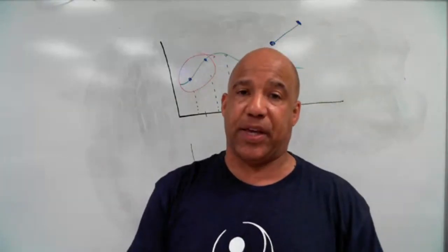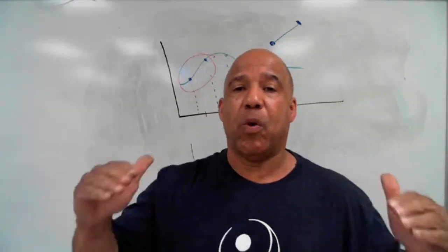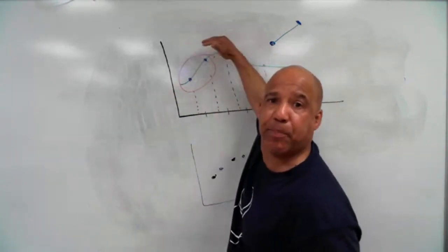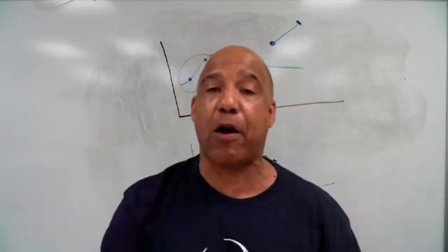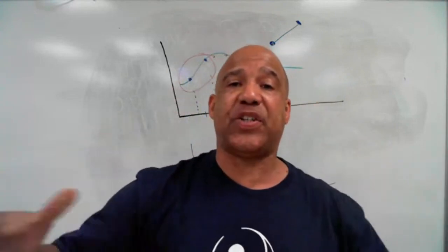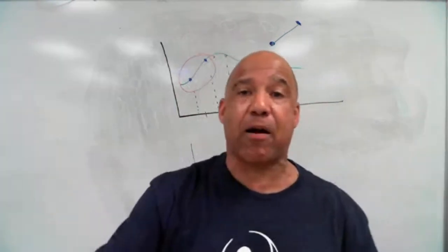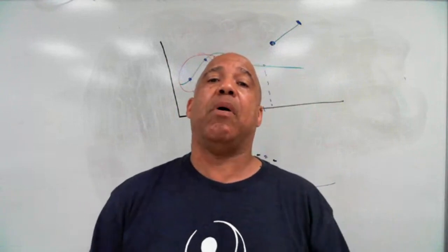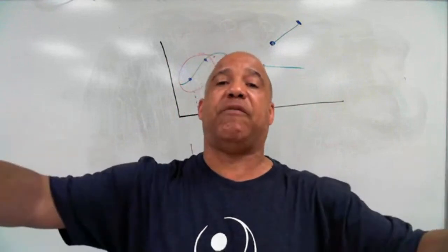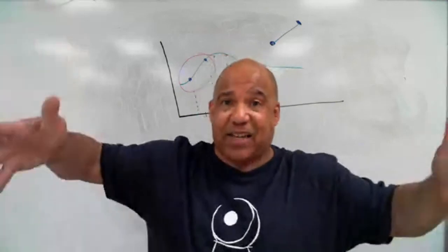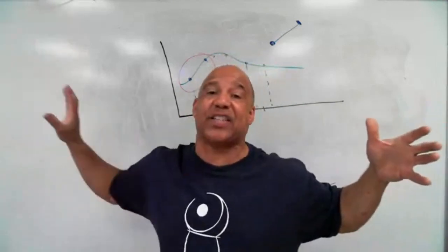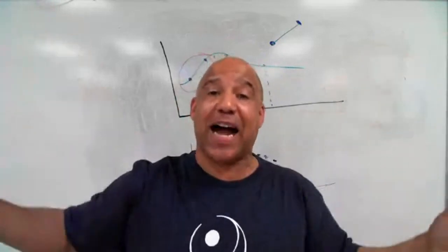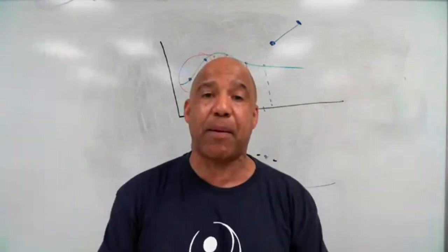The reason we have to talk about this is because of what we're going to do. In the old days, they would actually wire up relays in series and parallel, and I'm here to tell you it was a wiring nightmare. Every time something changed, you had to get electricians to come in and rewire parts of the circuit, or in some cases, the whole control system. When you have a control system, you have the logic part of it, and then you have the electronics that's actually controlling the system. Well, 85 to 90% of all the wires is just for the logic part of it. So it was a wiring nightmare.